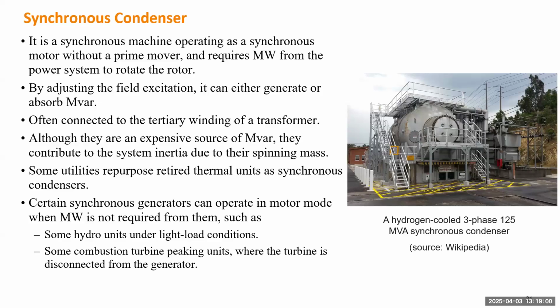But you keep the detailed synchronous generator model together with the exciter model, because a synchronous condenser has much better performance than any other controllers. So if that can verify your concept, then you can move to each individual voltage controller.